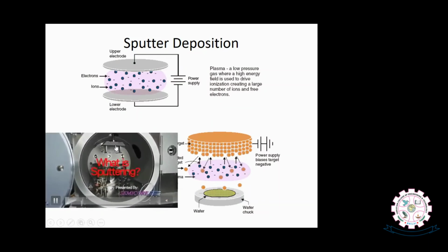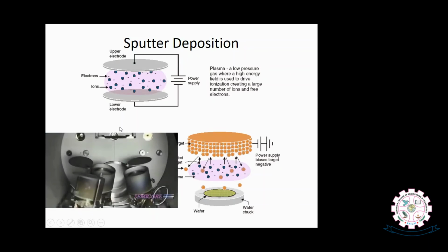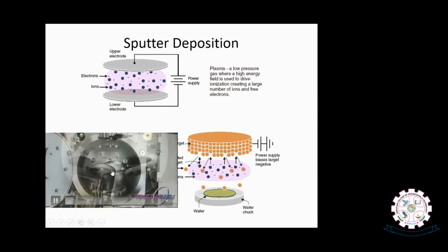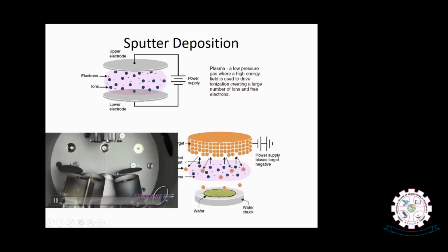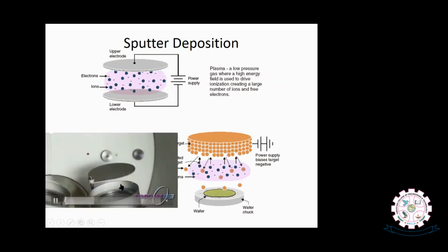So this is the sputter coater inside. You see, you will be able to move the substrate to get a uniform deposition here. These are the different anodes here. You will see how the deposition is happening. You see, the gas molecules will be entering the chamber, and these gas molecules are getting ionized here. The Ar will become Ar plus and 2 electrons minus. These plus ions are attracted towards the anode here, which are your target materials.